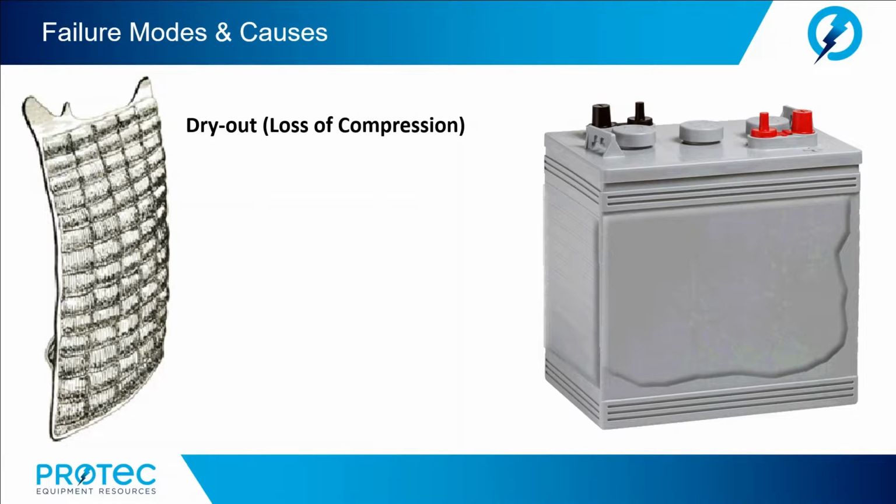Next, let's look at dryout, or loss of compression. Dryout is a catastrophic failure mode that can occur in valve-regulated lead-acid batteries. VRLA batteries cannot replace lost water. AGM separators become undersaturated and lose contact with plates. Excessive heat causes jar walls to bulge.